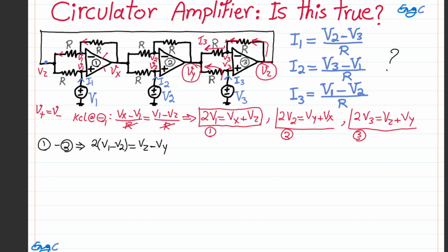So these two resistors, resistor R shown here and resistor R shown here, are effectively in parallel, because on one side, for both of them, we have Vy, as you can see.